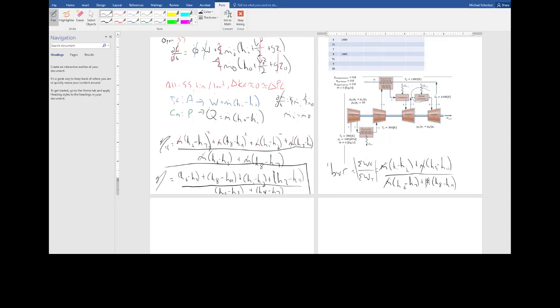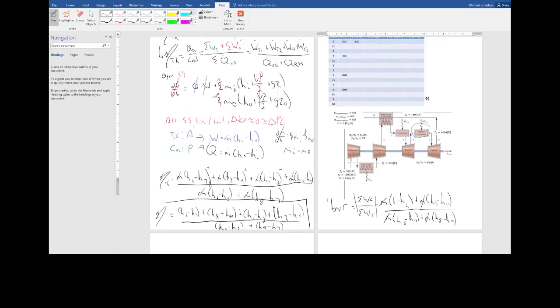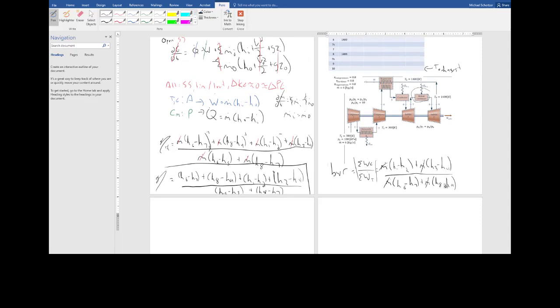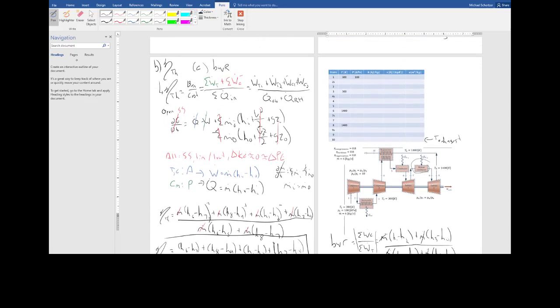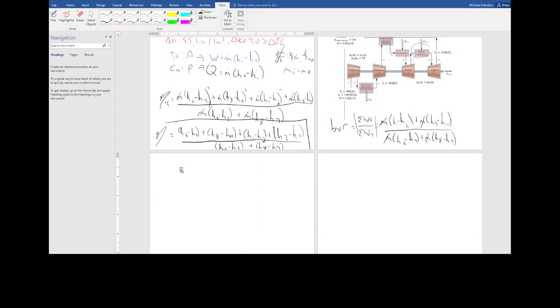So we got our symbolic solutions, which is great, right? But there's like 9 unknowns that we have here. Often, this question too might ask, what is T exhaust? So what's the temperature at state 10? We don't know. So now we have the exciting task of fixing the states.